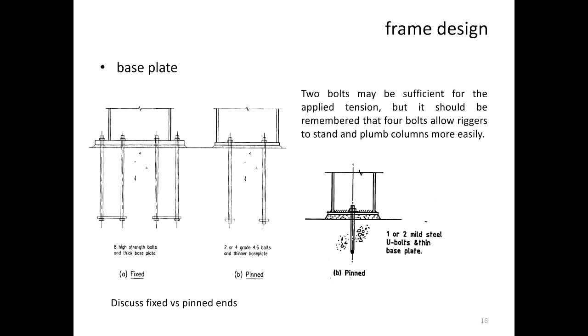Why is that fixed? Why does it say the column there is fixed? Yes, it does exist moments, of course, but why? From the drawings. Exactly, because the bolts go out beyond the flanges. So which means that is meant to take moment. So what happens is, if I push that column over, it's going to transfer bending across that base. So these are some of the exam questions. So the exam is not that difficult, it's just tricky.